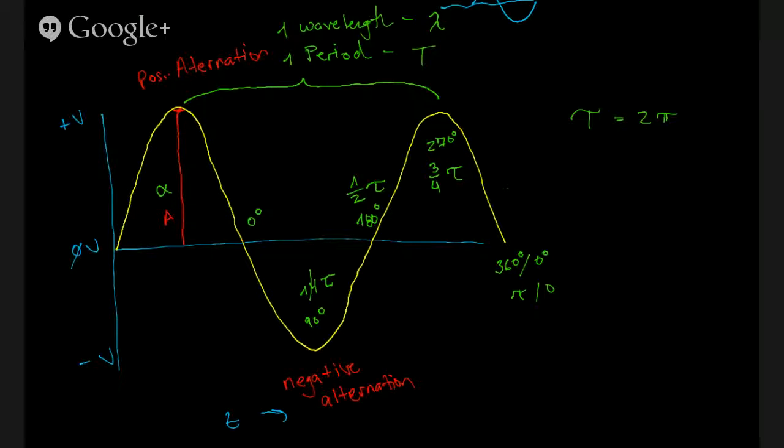What we want to do is we want to know how the voltage in this equates to an equivalent DC circuit. You might think it's the average. It's not. It's not far off, but not exactly the average. The average of a sine wave is roughly 0.636.